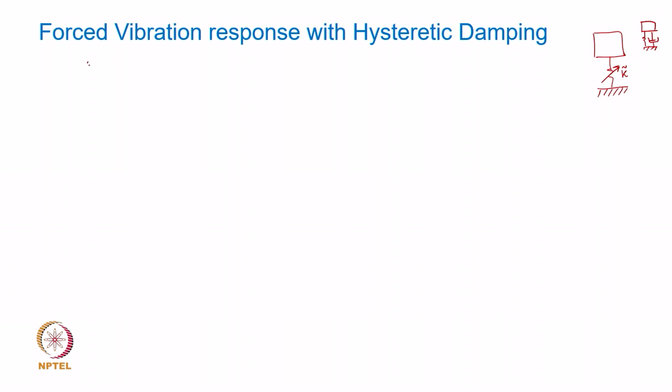So, what is our governing equation of motion? M x double dot plus this part, please revise and revisit all the discussion we had regarding the hysteretic or structural damping case for free vibration conditions, and we have that time derived that it actually turns out to be a complex stiffness times the response x, and now it is going to be F e to the power j omega t. Okay.